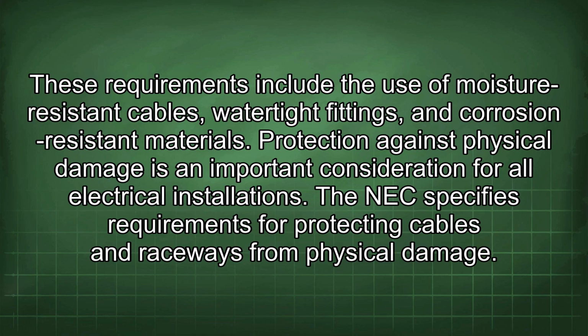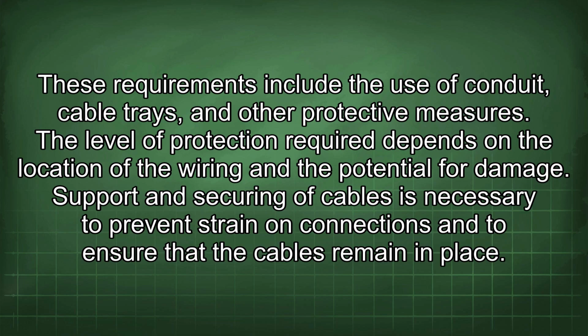Protection against physical damage is an important consideration for all electrical installations. The NEC specifies requirements for protecting cables and raceways from physical damage. These requirements include the use of conduit, cable trays, and other protective measures. The level of protection required depends on the location of the wiring and the potential for damage.